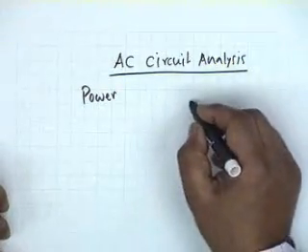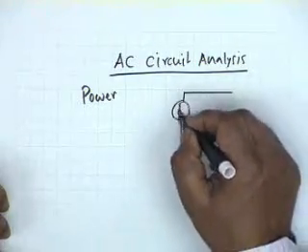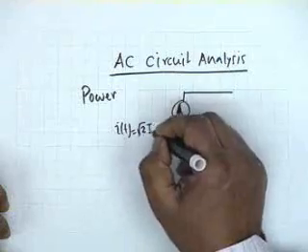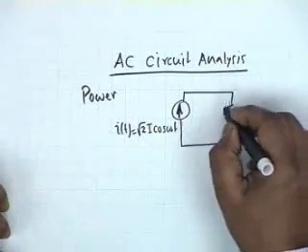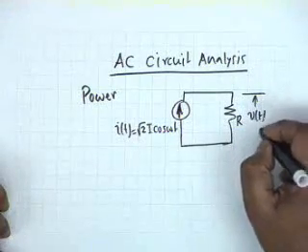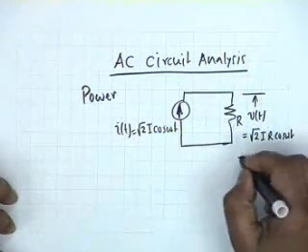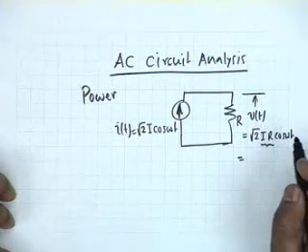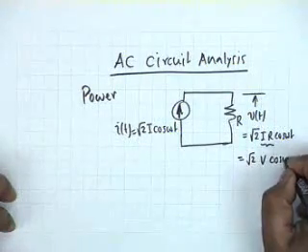As you know, if we have an AC, let's take a current generator, I of t is equal to root 2 I cosine omega t, and let this current pass through a resistance R. Then the voltage across the resistance v of t shall be simply equal to root 2 I R cosine omega t, and if we call I R, where capital I is the root mean squared value or the effective value, as V, then v is root 2 V cosine omega t.